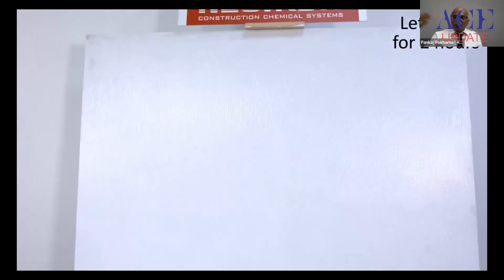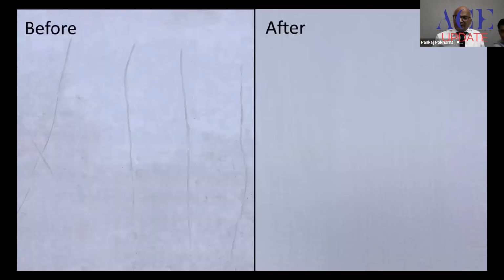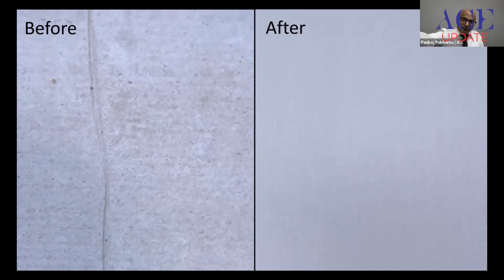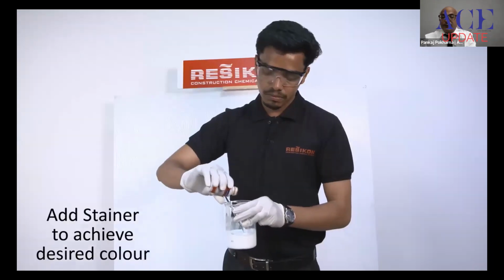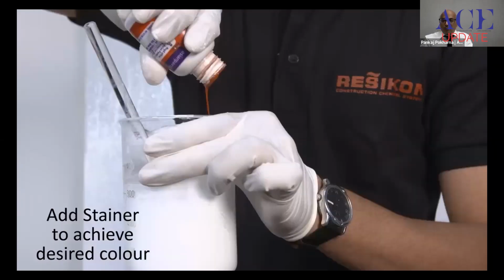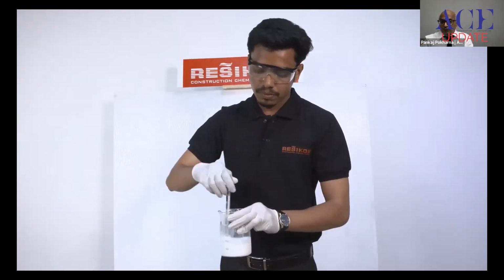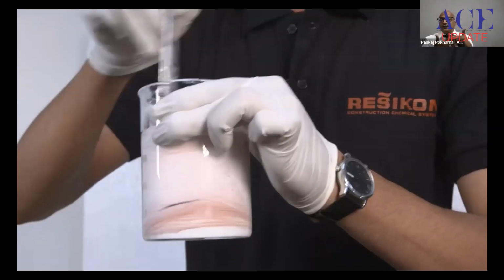When it dries, in 2 to 4 hours, in summer it takes 2 hours, in winter it takes 4 to 6 hours, for monsoon areas. You can see before, these cracks are there, and when you coat it completely, these cracks are also hidden behind the coating. This coating has a crack bridging ability of 2 mm, so up to 2 mm cracks can be hidden behind the coating.